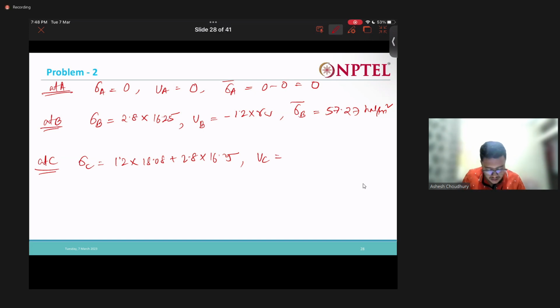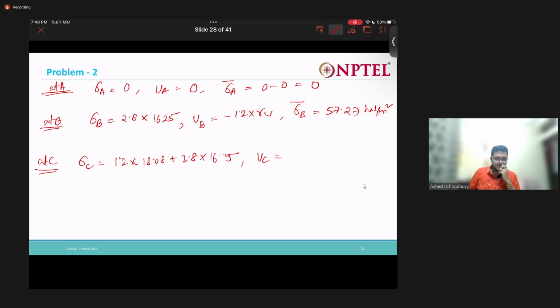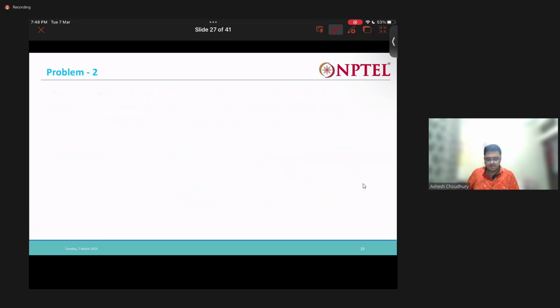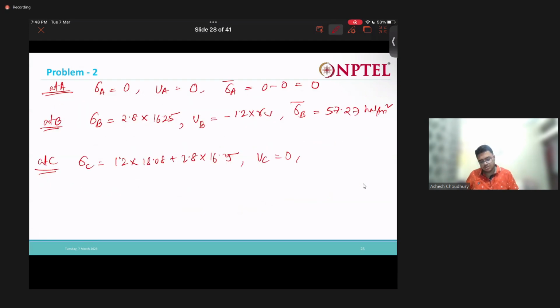What will be the pore water pressure at C? It is 0, right? So my effective stress will be equal to this total stress.